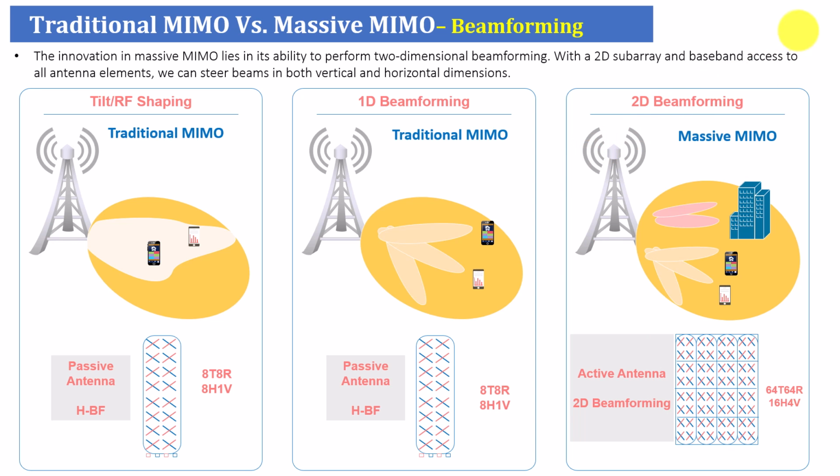And this was just a quick, not very quick to be honest, summary about the gains. Whatever gains you have now in massive MIMO were already covered by the traditional MIMO, but they will be much higher now because of more antenna elements, which give more control, sharper beams, and more directivity for the beamforming. You will have both horizontal and vertical planes, called the azimuth plane and the elevation plane. So this is called 2D beamforming, and more details will be covered in the next slide.